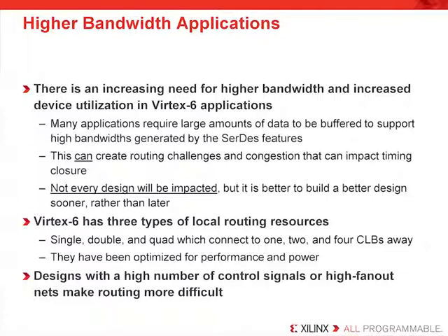Now, not every device or design will create routing congestion. It will simply vary by the device utilization and the purpose of the application you're building. But it is important to use these design techniques, which will greatly improve your chances of avoiding a routing congestion problem. You should also keep in mind that it is not just the fact that you use control signals in your design, but if you build them efficiently, that is more important.